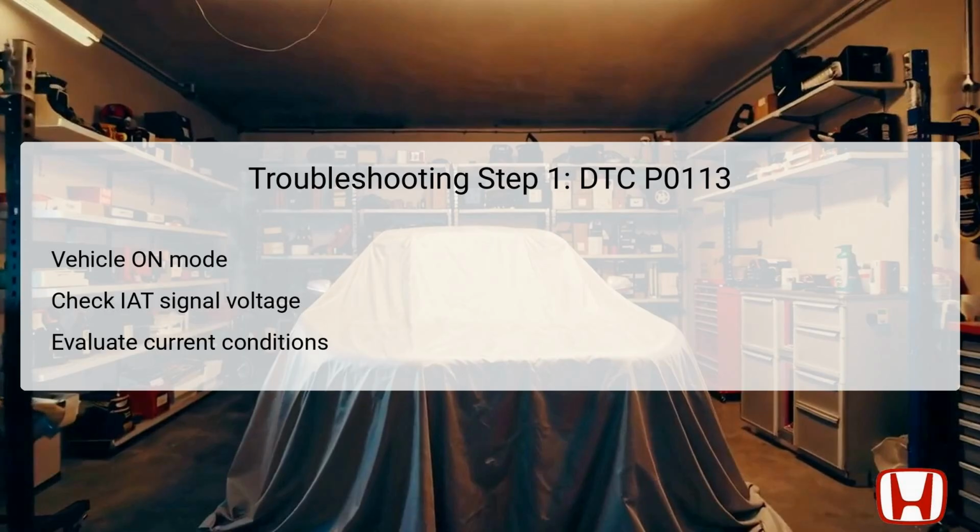However, if the voltage appears normal, it indicates an intermittent failure, possibly due to poor connections or loose terminals at the MAF or IAT sensor. Checking for freeze data or onboard snapshots may help in replicating the failure under specific conditions, aiding further diagnostics.